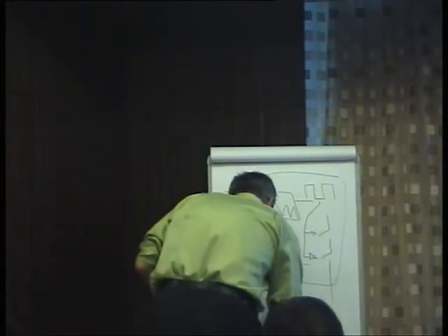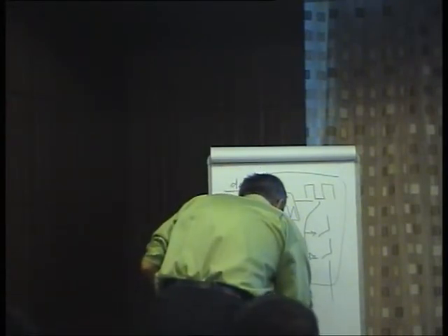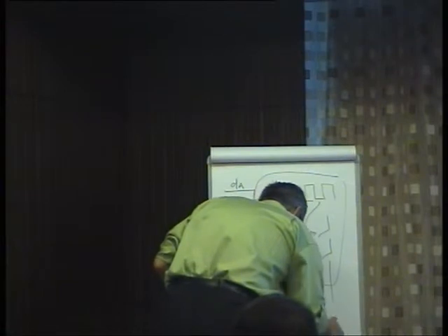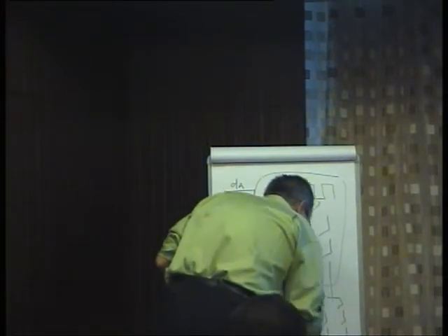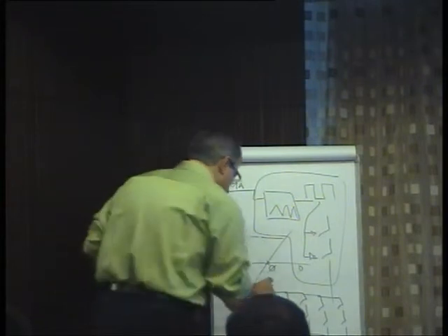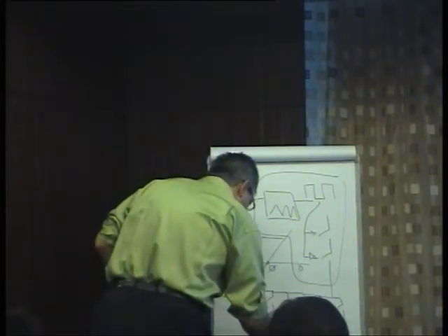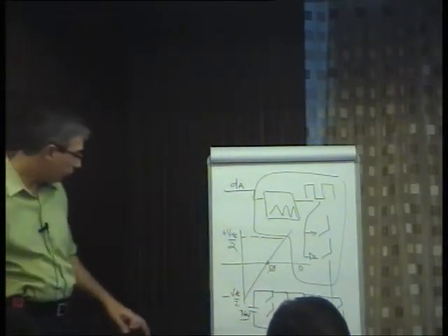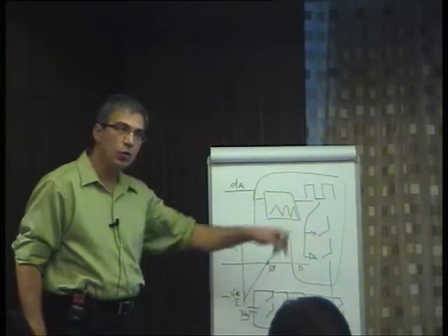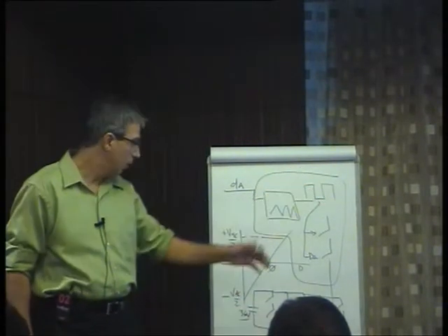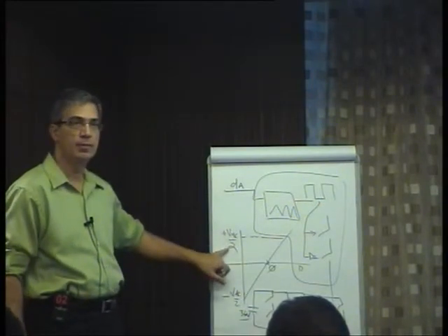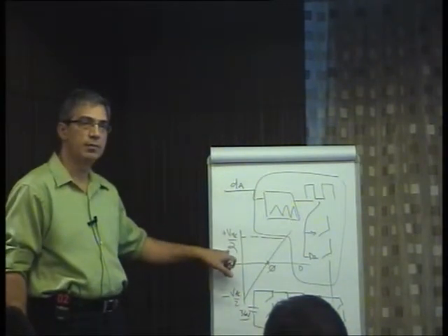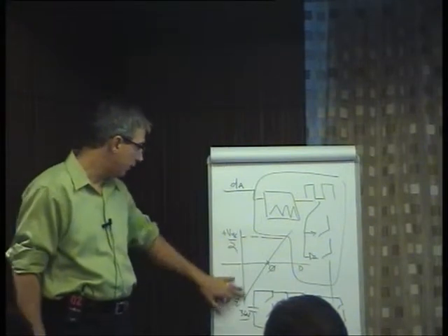So if I look at the inverter, see this here may be 36 volts. Since this is 36 volts and your neutral is going to be roughly at 18 volts, the available voltage is only VDC by 2. So across the winding, you are putting VDC by 2. So the transfer function is like that for the inverter.